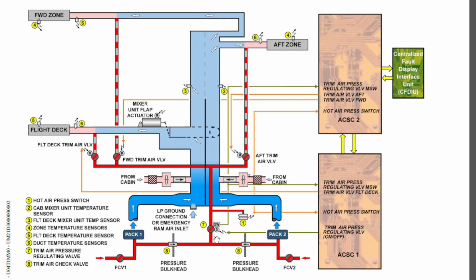In case of failure of the valve, if the pressure increases above 6 psi, which is the threshold set by the manufacturer, that pressure can damage these hot air ducts.